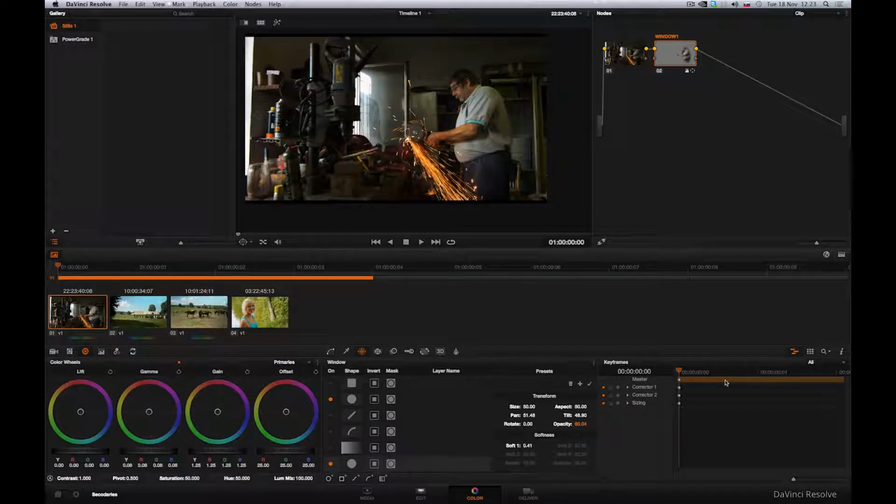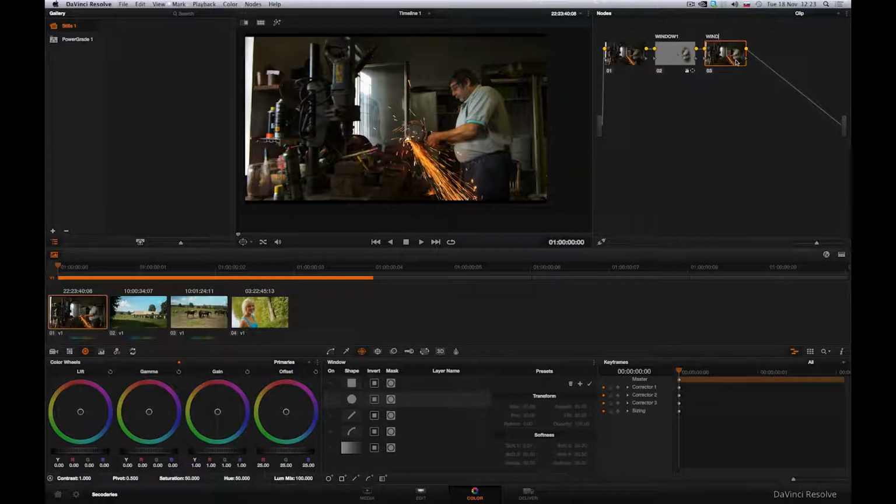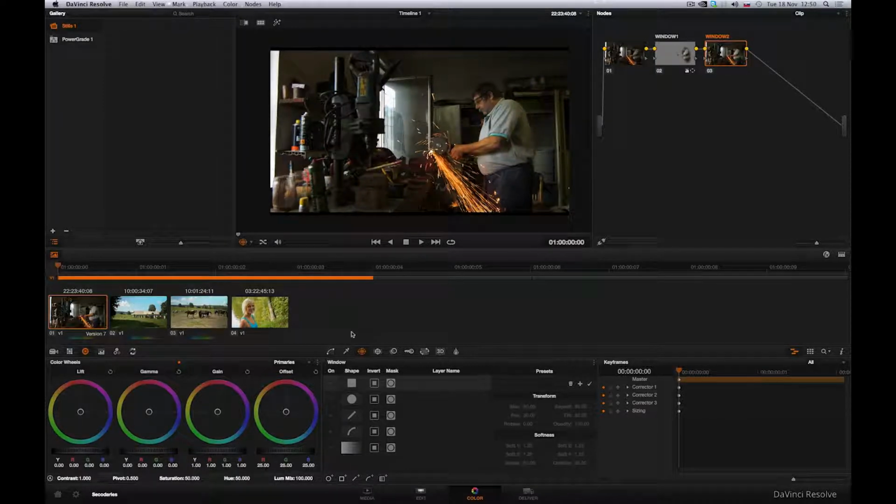Picture sections can be brightened but also darkened, of course. I'll create another node. Next, I darken, for example, the glass on the window, which seems too dominant. Select the linear window and move the points to their appropriate spots. Lower the gamma and gain.